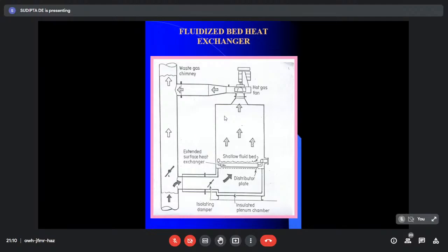One is that the heat transfer characteristics improve, because rather than only a gas-solid mixture passing over the heat exchanging surface, there is more contact. But as the heat transfer increases, there is simultaneously a significant erosion problem. So optimization between the erosion and the heat transfer coefficient is an operational experience decision. In fact, I still know many companies that operate fluidized beds and have their own database for deciding at what air velocity they will operate, to maintain a steady, stable bed while keeping erosion optimized. But now I'm coming not to the entire broad area of fluidization, but only to the fluidization heat transfer characteristics for waste heat recovery.